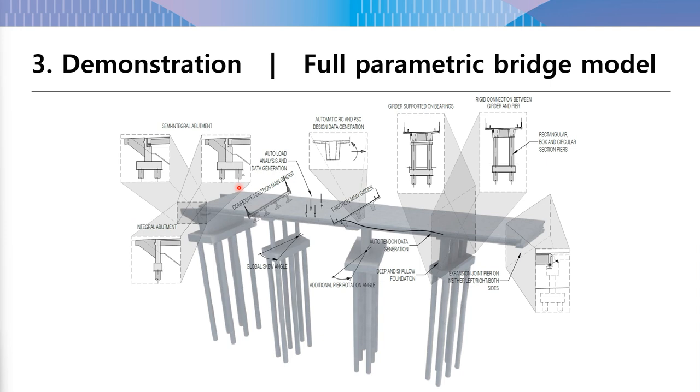Also, it automatically generates all of the seismic load cases, and it automatically combines all of these loads and generates load combinations required for design according to Eurocode.